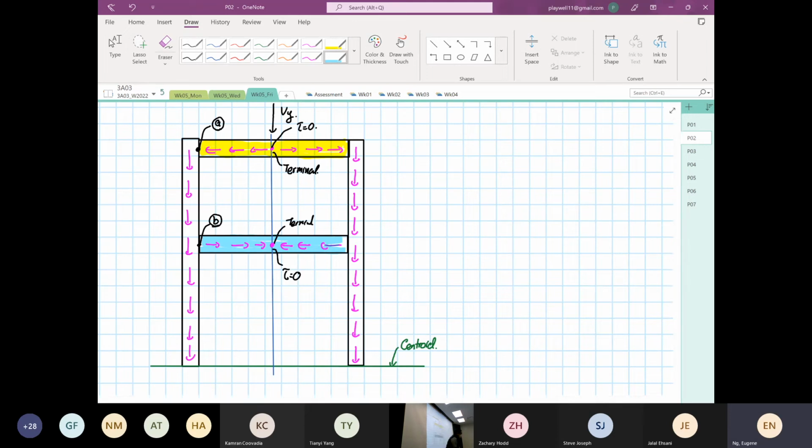I want you all to hear me out. This is the stage where it's confusing, but hear me out. In terms of fluid flow, take the two vertical webs as your mainstream. You understand what I mean by mainstream? It's where the shear flow will want to go. It does not want to come in. It wants to go down the mainstream.